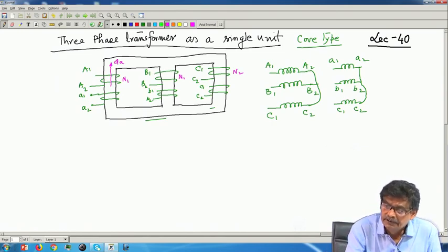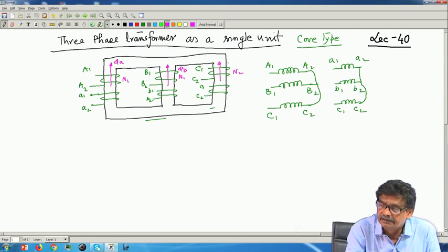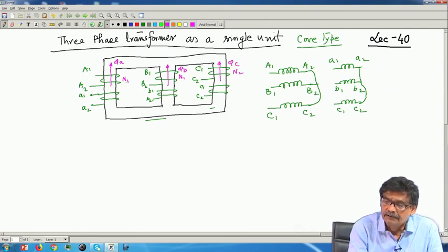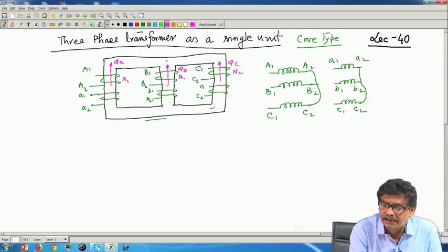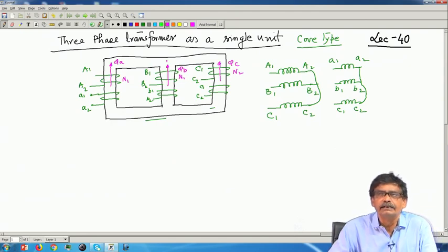Similarly, if this supply voltage is balanced, phi B will also be like that, its strength, and phi C will also be like that, getting the point. Now, these three fluxes, as if we presume they come here and meet, they vanish, because phi A, phi B, phi C are 120 degrees apart, clear.